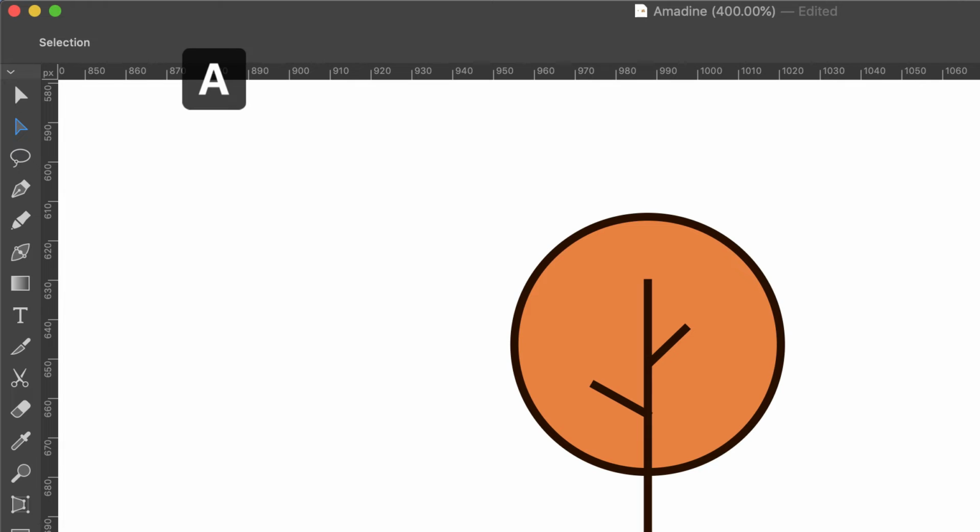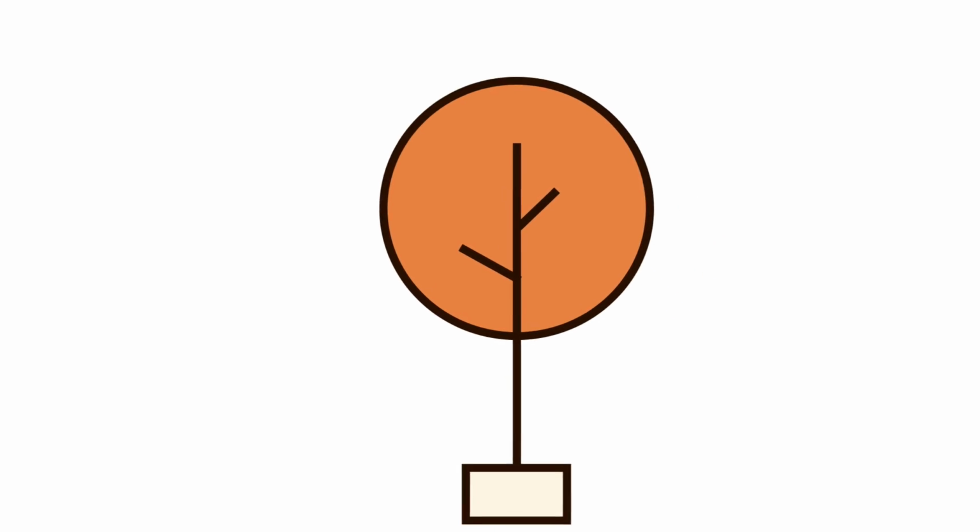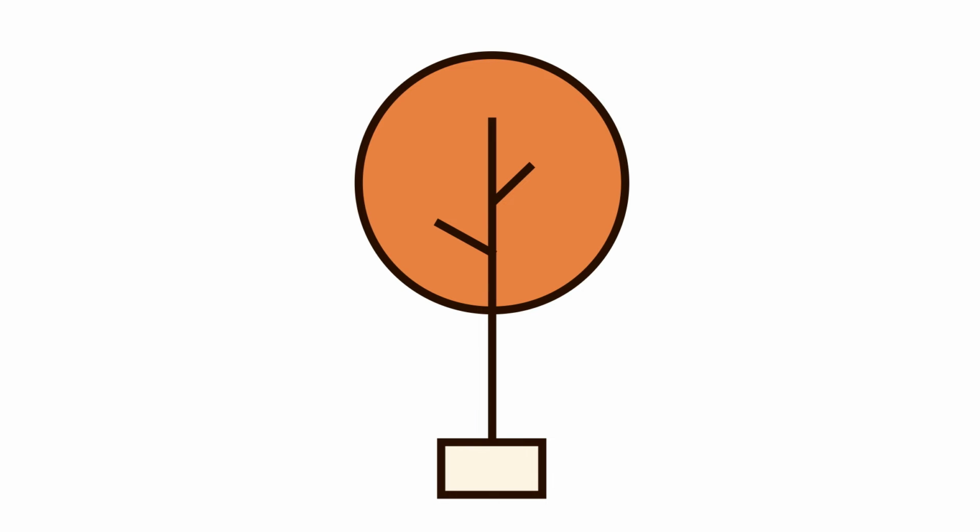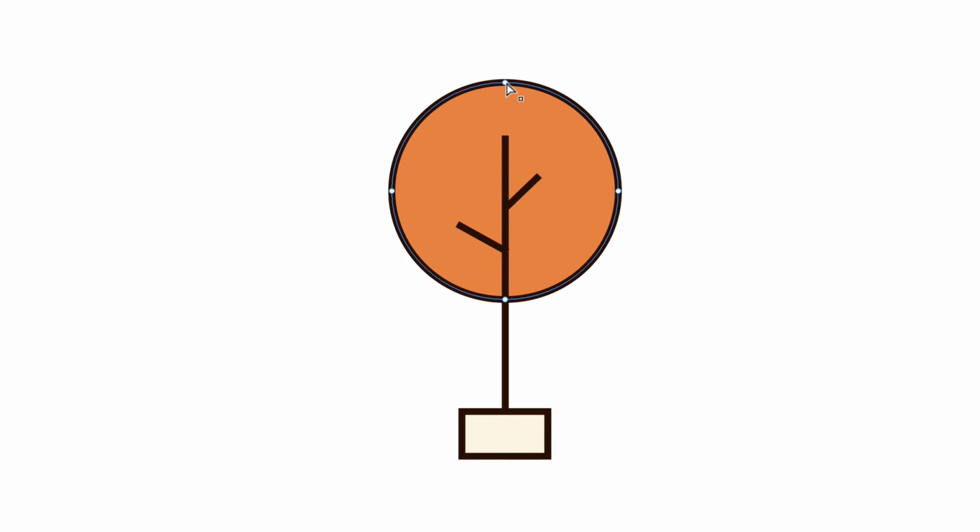The purpose of the selection tool, which we activate by selecting it in the Tools panel or by tapping A on the keyboard, is slightly different. It is used to select anchor points that form a shape. Once we click on any shape or path, we will see all points and line segments that form it. To modify a shape, you can drag one of the points.